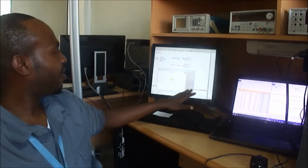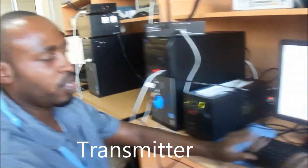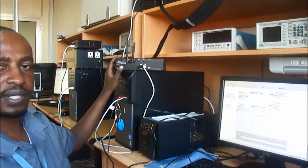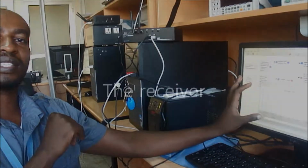Here we have a transmitter TX1. We also have a transmitter TX2. This transmitter is based on the frequency range of 2.4 gigahertz. It's going to be transmitting to the far end receiver. The transmitter is using a USRP component that is communicating with GNU Radio software. It is TX1 and is transmitting at a different amplitude from the transmitter TX2.